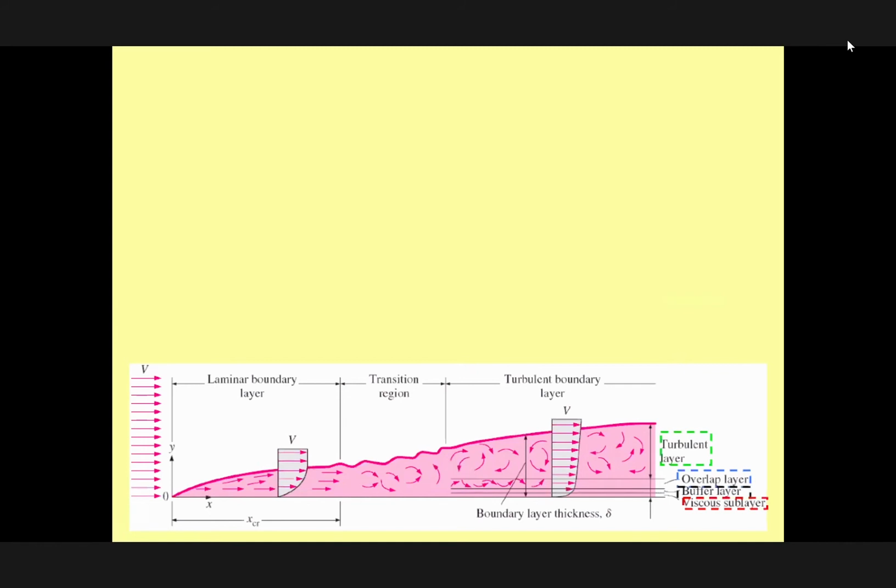That's the physics of it that you should understand. This boundary layer is growing slowly, slowly, and the other one is growing down from the top. But since they are identical plates, the velocity profiles have the same force against each other. Therefore, they meet each other at the center.